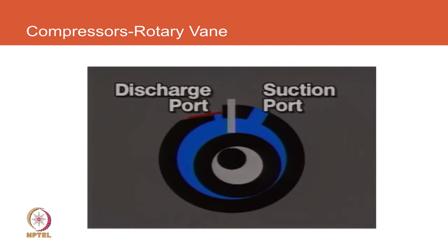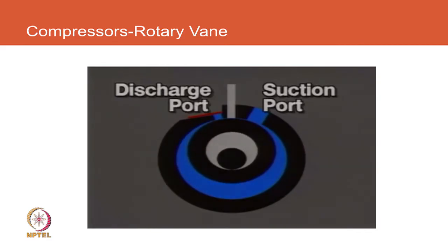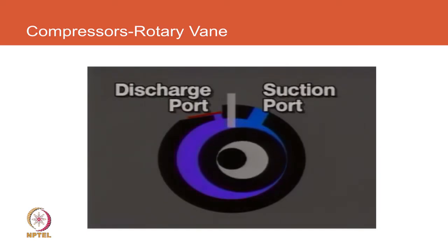As we move, we can see the space on the left getting smaller, and therefore the pressure going up until it is almost negligible and the entire refrigerant is forced out, and a new set of refrigerant molecules are there to again get compressed. So this whole thing will continue, and every 2 revolutions we would have moved refrigerant from the suction side into the discharge.